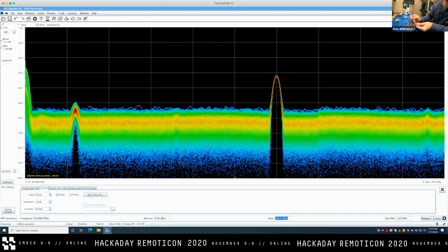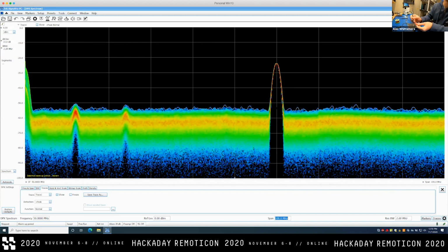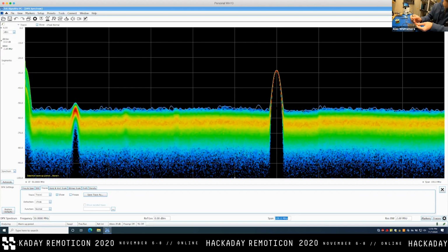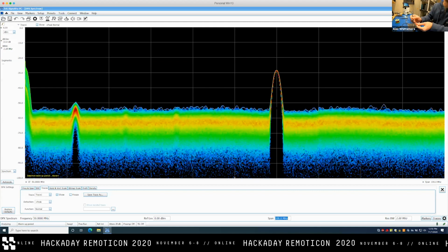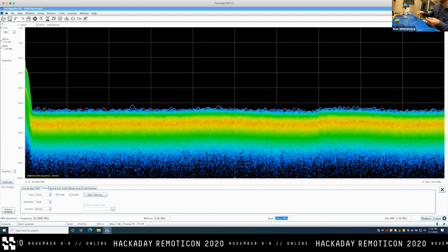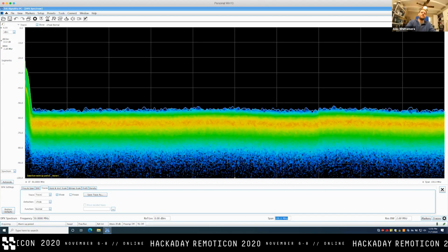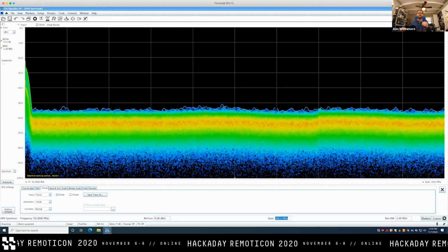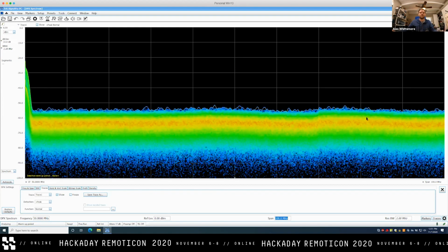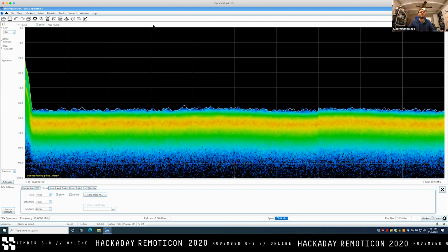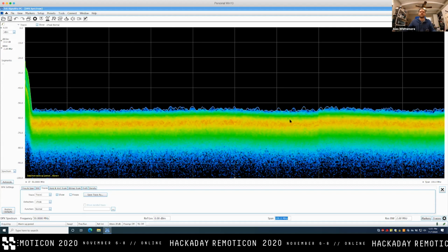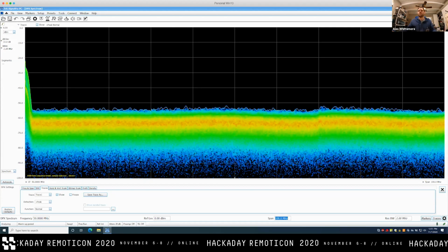But this gives us a much more interesting idea of, if I go over here and measure, let's say, that 60 megahertz thing, what's actually happening on that signal. Okay, the peak that we were measuring earlier is very indicative of how much RF power is actually going on there. And you can see why this gives you a really good visual of what's going on if you are operating in a frequency range where you can tune to it. And we'll see later, while the other tools don't necessarily scan the frequency to give you a wider than real-time bandwidth like this, at least SDR Angel does give you this sort of digital phosphor view that can be super useful if you're looking at a range that's relatively more constrained.